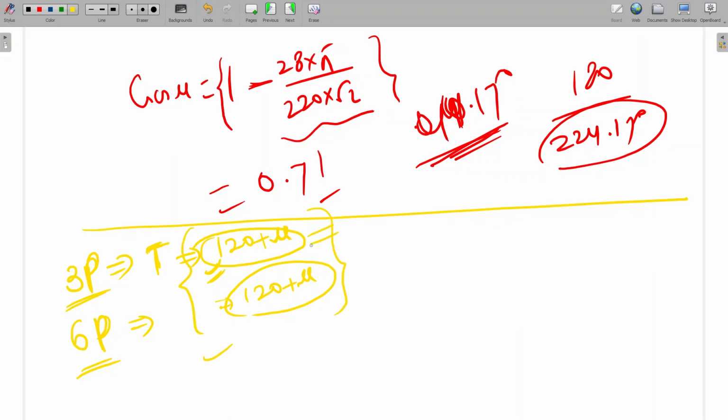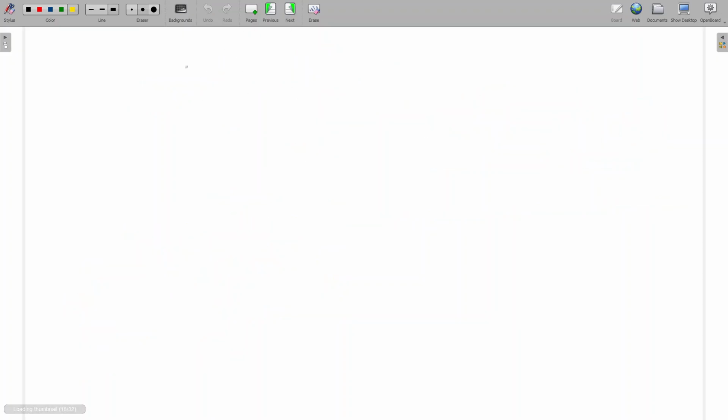Like first we'll calculate the value of mu. After that, if the question is what will be the conduction angle of the thyristor, normally it should be 120 degree, but if mu is there, it will be 120 degree plus mu. Okay. So I can give a little bit of overview. Let's say this is a 3 pulse converter. So we can draw the waveform like this.